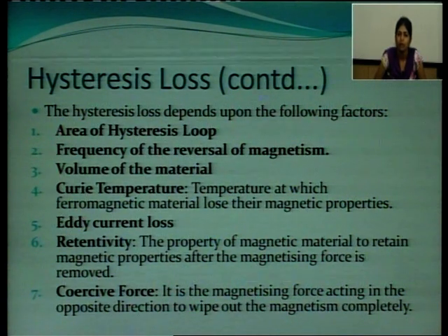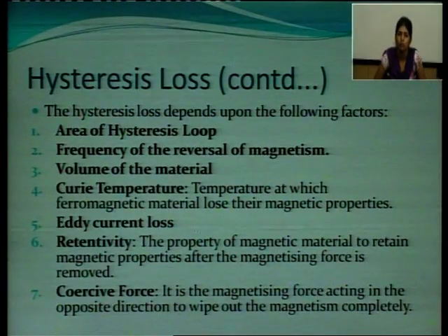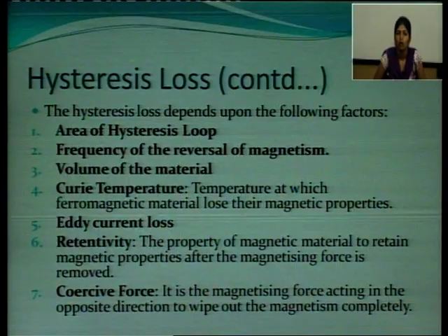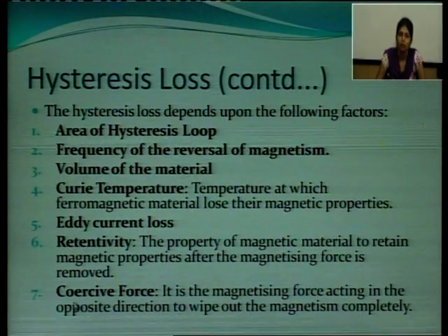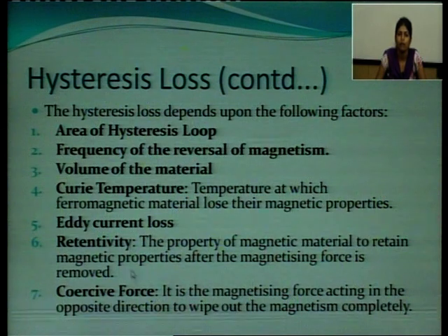Retentivity is defined as the property of a magnetic material to retain the magnetic properties after the magnetizing force is removed. The next is coercive force. It is the magnetizing force acting in the opposite direction to wipe out the magnetism completely. So, more is the retentivity, more is the hysteresis loss, and more is the coercive force, more is the hysteresis loss. All the factors are directly proportional to the hysteresis loss.